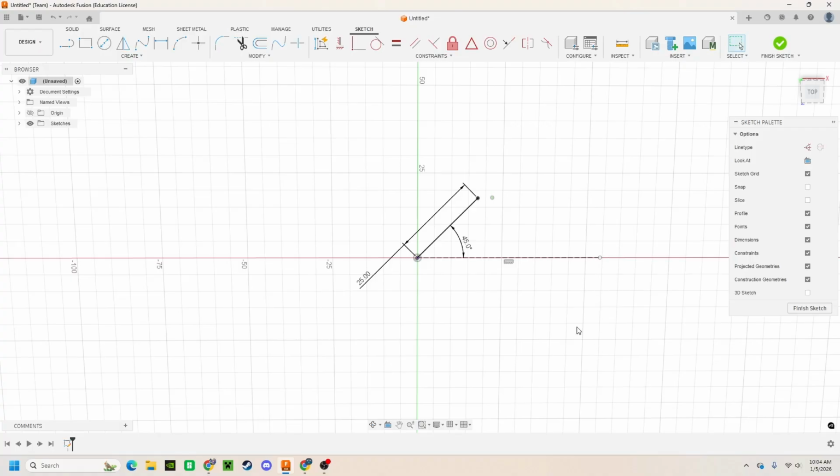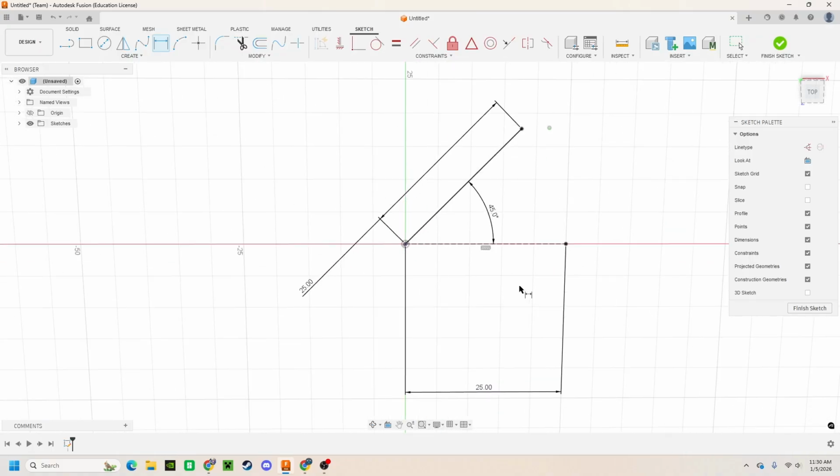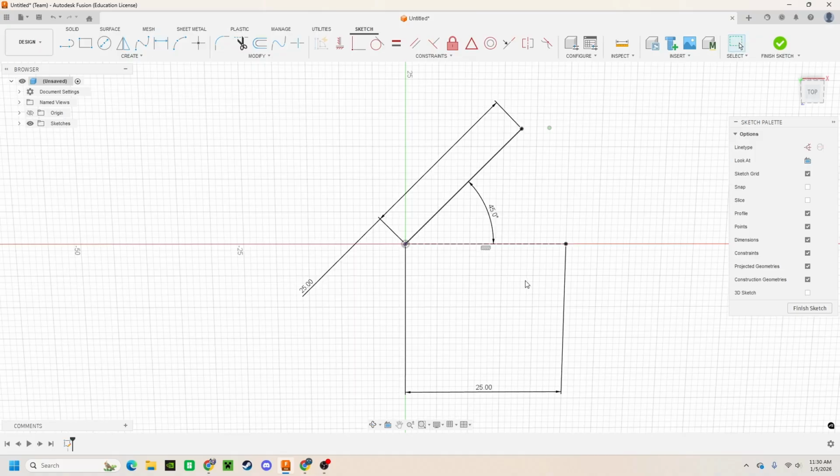We'll also notice that when we create a line like this, it also creates a secondary construction line. This construction line's distance is unconstrained as well. We can constrain this by giving it a dimension itself. The Dimension tool is the main tool in our arsenal for constraining objects. It can be used to define a length, a position, and an angle, as well as a distance between two objects. All other constraints are just some derivation of the Dimension tool.